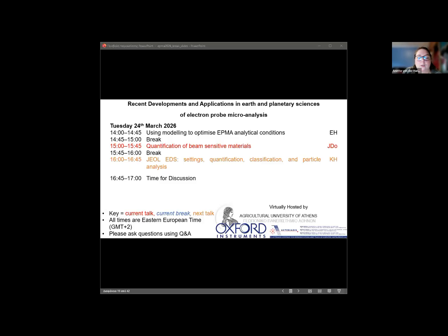So what I tend to do, specifically as using TDI at times can have some time overhead, is you can always test it. Just go on the sample at the conditions that you think you want to run it. If you have no idea and you don't have access to TDI corrections, the minimum that you can do is put the beam on and observe the absorbed current. JEOL has a nice chart recorder in its system, but you can otherwise just look at it, and ideally you shouldn't see a relative change in observed current over the time of your analysis.